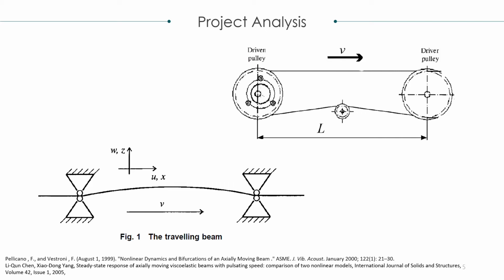For now, I would like to point out that W is associated with the transverse motion, while U is representative of the longitudinal motion, which is only considered to build the equations of motion, but more on that shortly. Out-of-plane motion is not considered. Also, the density and the cross-section are considered to be constant throughout the belt.